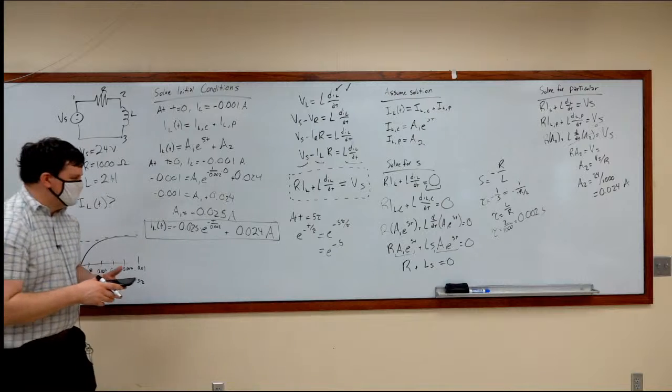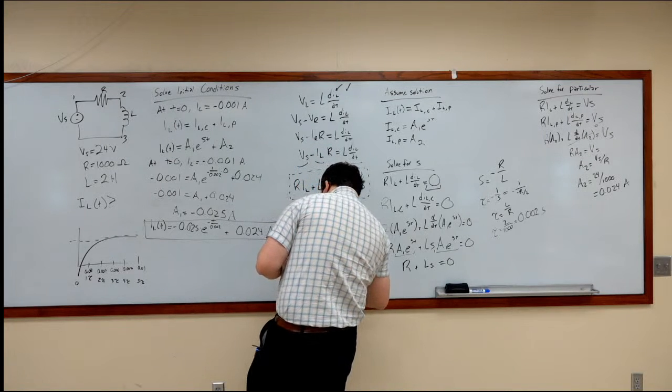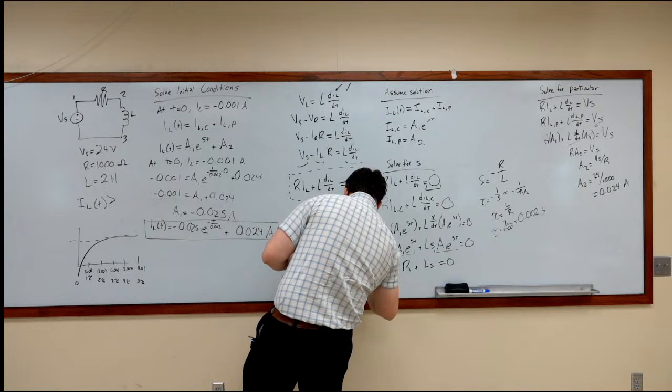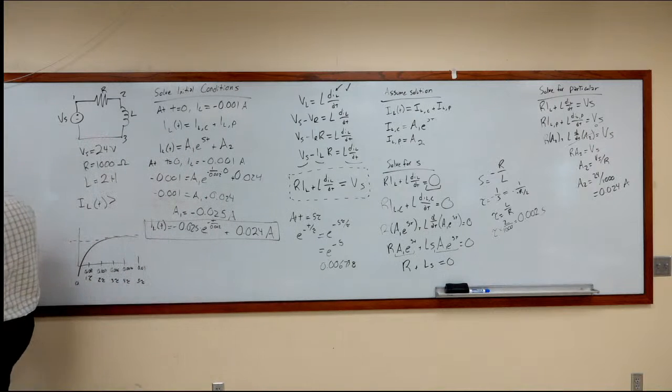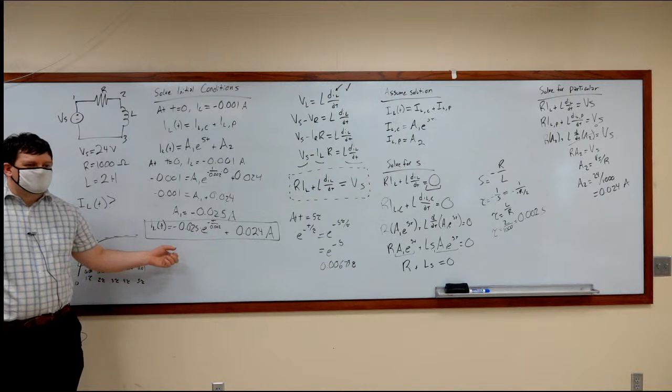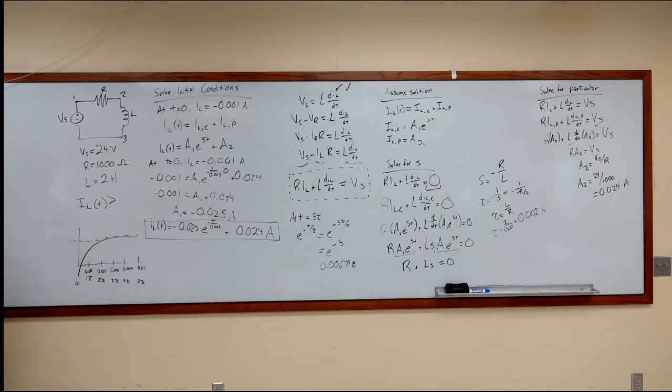The value of e to the negative 5 is 0.006738, which quite frankly is less than 1%. What that means is that at 5 tau, your function, the transient, is contributing less than 1%, really 0.6% change to what the solution actually is.